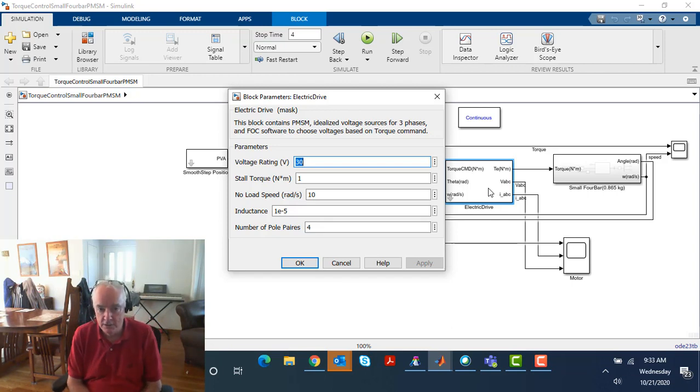If you're going to buy a motor, the process is usually to go online now and interface with these motor catalogs, and they're just going to give you a big list of probably like 100 motors, and you choose based on your requirements. Your requirements are going to be expressed in terms of voltage rating, stall torque, no load speed, and in general, you simply allow the inductance choice to be dictated by what's available in their catalogs. And I think number of pole pairs would probably fit that too. Okay. But anyways, at this point, we're pretty close to done.